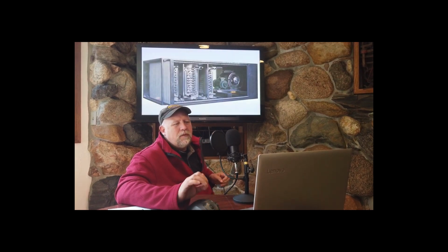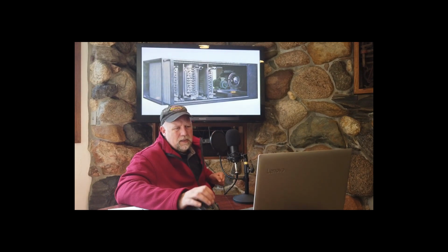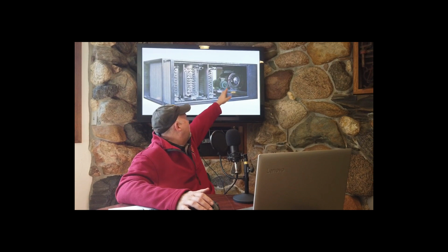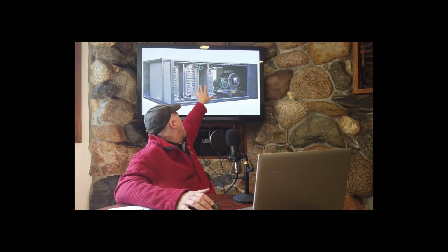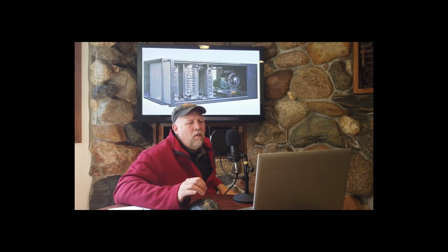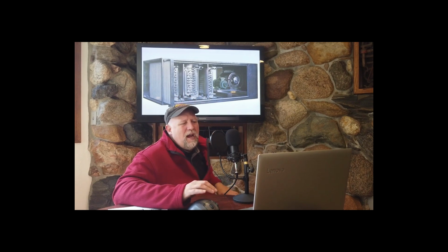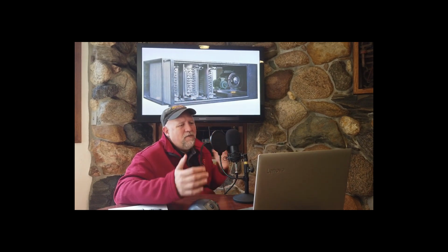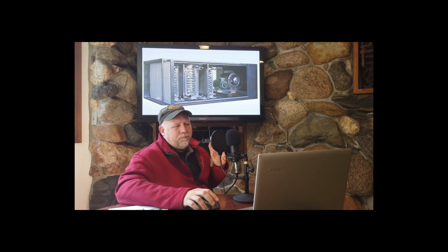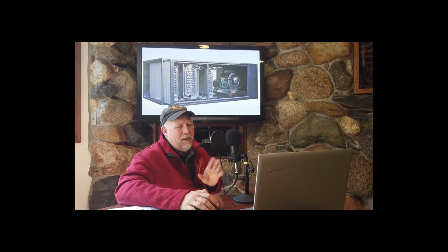Here's a simple, small one with the side removed. Here's a supply fan blowing upwards with a motor and a belt drive. Upstream of that, we've got some heating and cooling coils and then just a filter section. This is a very small one, very simple. It doesn't have the mixing box. It doesn't have a return air fan, but it has what I would call the basics. Heating and cooling coils, filters, and a fan. That's as basic as it gets.